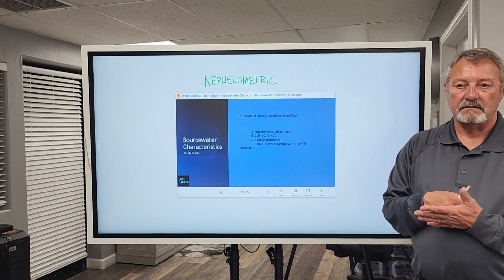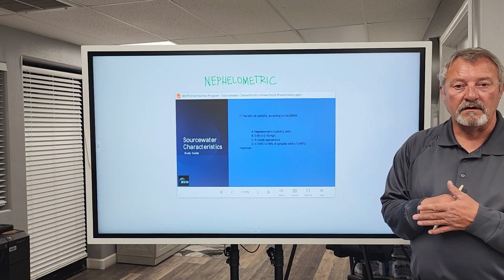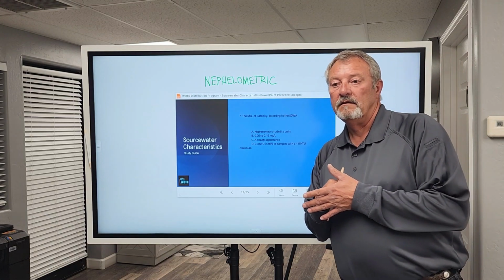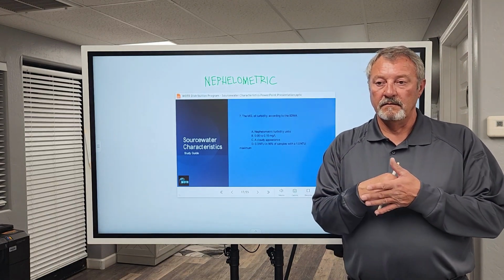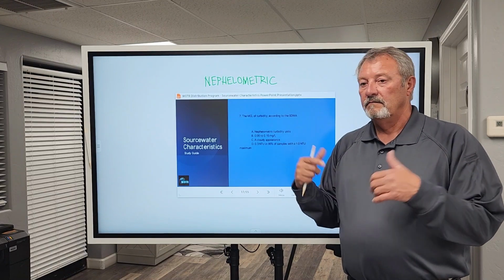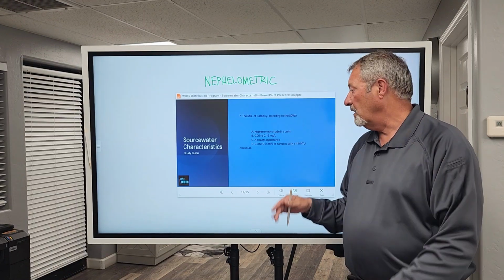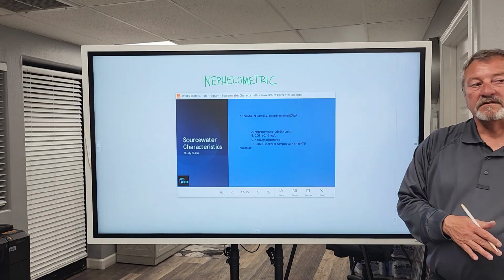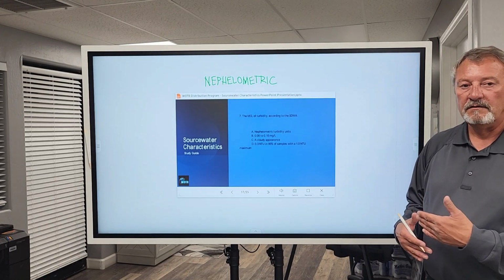There's a violation. There's something wrong. The important part here is that the water treatment plant operator is paying attention, that they're getting the alert, the alarm, the notification that, hey, something's wrong, filters are bound up, there's some issue going on, you just exceeded 1 NTU. Hopefully they get that alarm before it's exceeded, so they can do something before that happens.